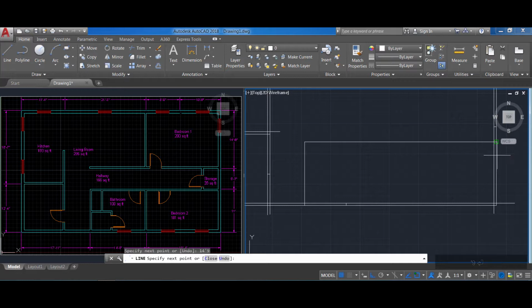and then the rest one I'm just gonna keep going here. I'm just gonna extend it like this. Then I'm gonna press the spacebar again, and I'm gonna go in my first endpoint, because I know this is the end of the room. So I'm gonna do this, and I'm gonna draw some construction lines here of 1/2 inch, so I can create my walls. Enter here, spacebar, 0, 5, then I'm gonna go down here, spacebar, and here,